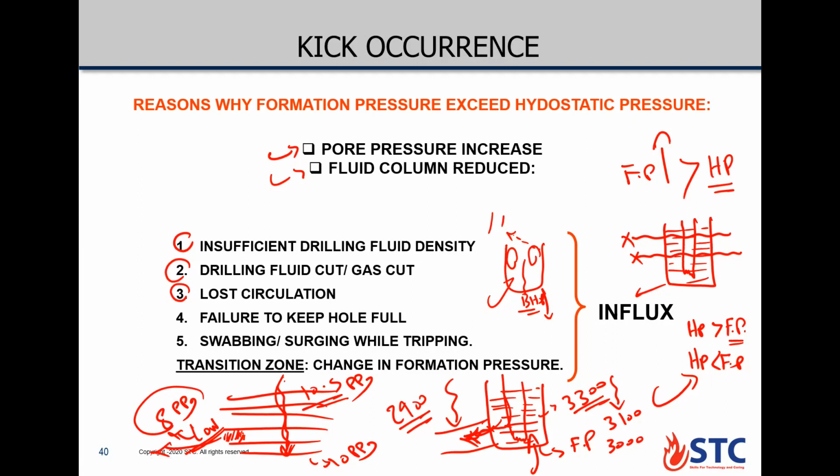Once losing mud weight here and completing drilling to the further formation, you're gonna face here 10 ppg, and you already lost some fluid in this formation. So if the level drop in your hydrostatic pressure in this situation is not sufficient to be still over 10 ppg, you're gonna have influx.